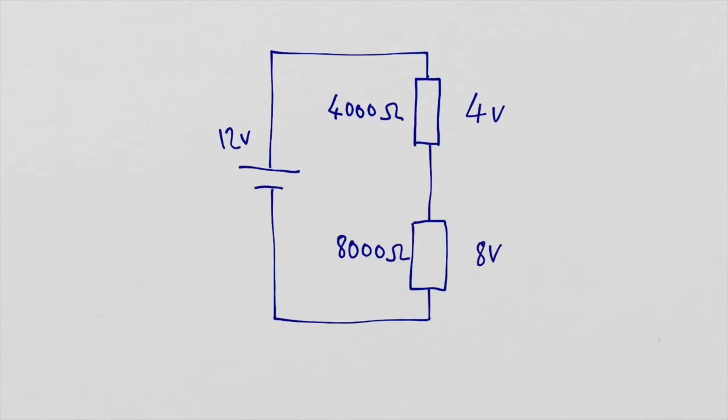We've got a really interesting situation now. The resistance isn't the thing that tells us what the potential difference we're going to get is. Changing the resistance doesn't affect the potential difference that we get out. It's the ratio of those resistances that affects the potential difference. In this situation with 4,000 ohms and 8,000 ohms, we're going to have a lower current than on the previous version, but in terms of the potential difference, the result is the same.